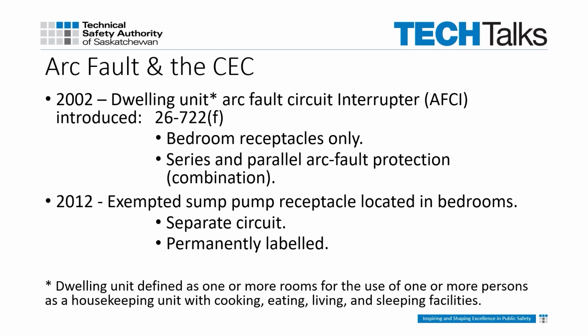Ten years and 3 code cycles later, the CEC added an exemption from AFCI protection to any dedicated permanently labeled sump plugs located in bedrooms. The exemption was added because the sump motors tended to trip the AFCI due to the sparking nature of motor operation. And we all know that tripped sump pumps make for impromptu basement renos, and those aren't that much fun.